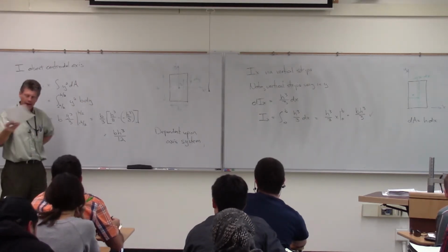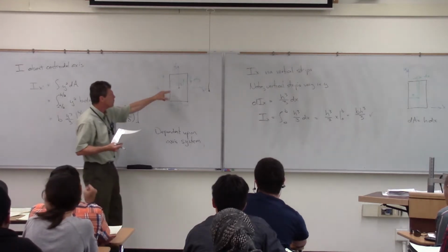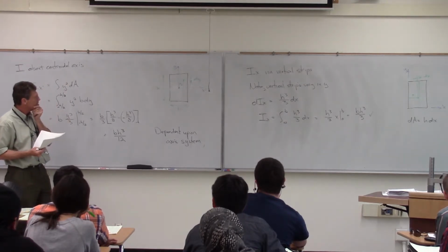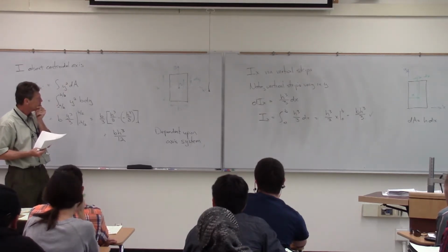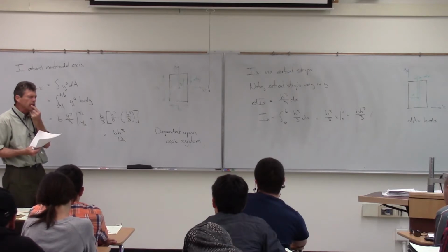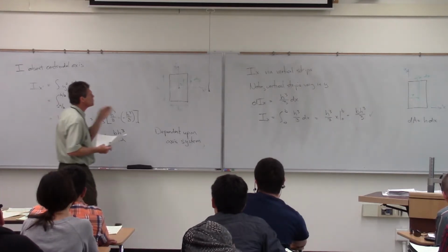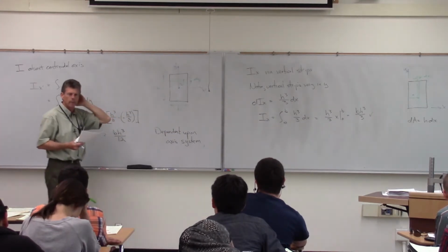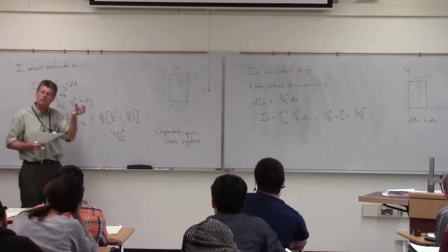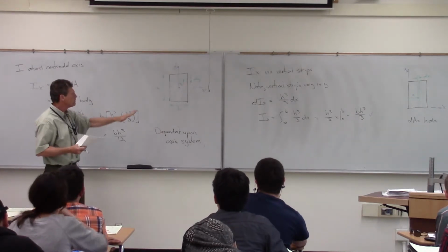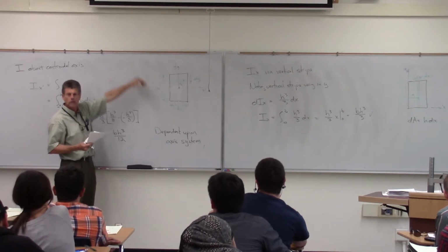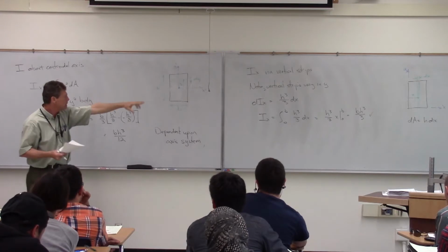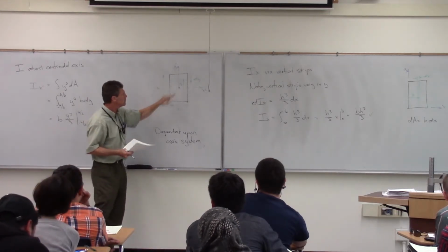Well, and I will write it out. But basically, as you know, what we're going to see then is that the smallest moment of inertia is going to be at the centroid there. And when you think about it in terms of when you're going to be dealing with stress, it's going to be bigger if we have pieces that are farther away. And that's the concept behind things like eye sections and stuff. What we're going to find is that most of the stress is going to be out there at those far points. So we want to get as much material out there to do the work. And that material in the center here basically isn't going to be doing much.